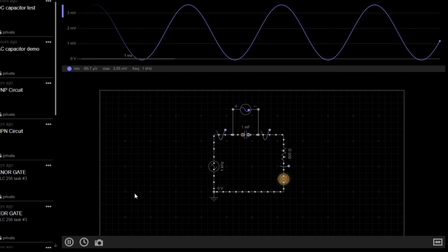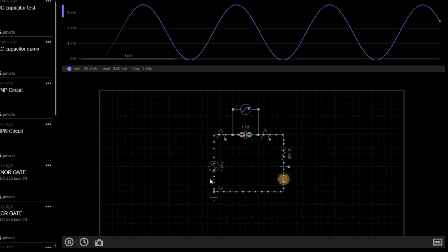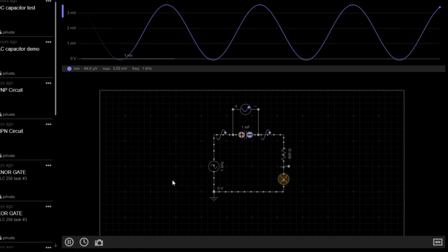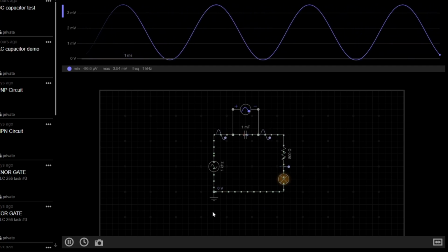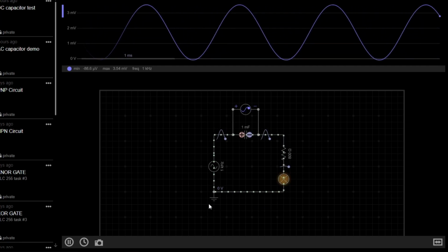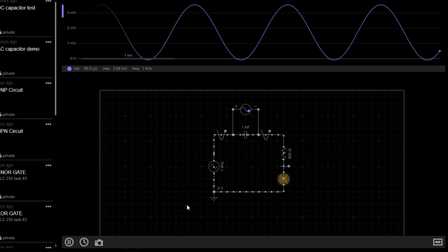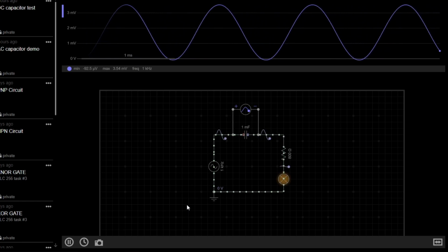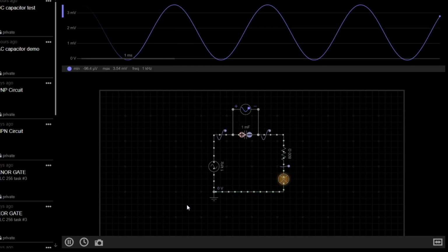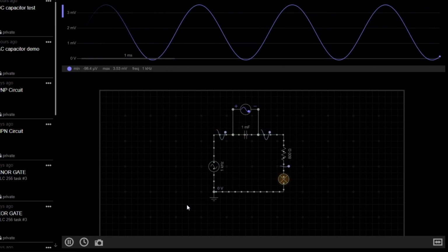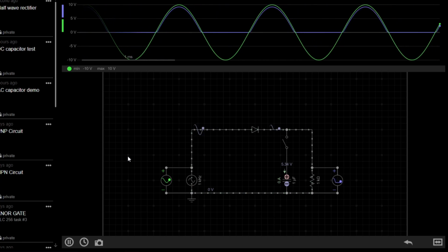If we now look at the same circuit, but with a 10 volt peak alternating current supply, we can see that the capacitor regularly charges and discharges, and the bulb flashes on and off, without me having to do anything. In this manner, capacitors in series allow AC to pass freely. This means a capacitor has the ability to remove DC from an AC signal, which is extremely useful throughout many electronic applications. Capacitors also have uses when you have an AC voltage that's been through a diode.